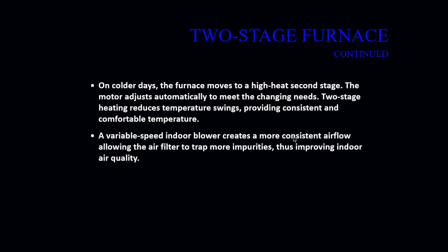On colder days, the furnace moves to a higher heat or a second stage situation, or what we call high fire. That motor adjusts automatically to meet the changing needs. In those two stages, heating reduces the temperature swings, and it provides a more consistent and comfortable temperature within the space.